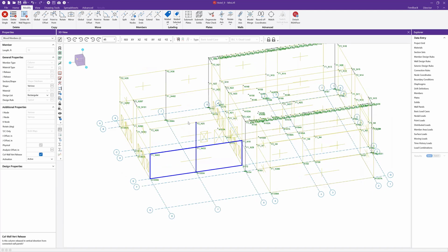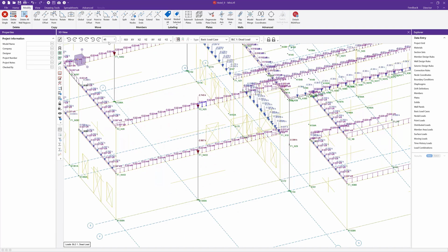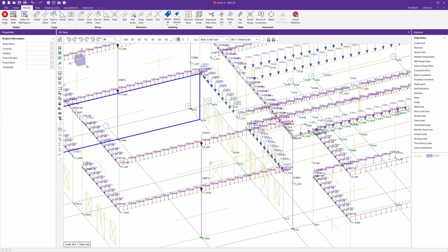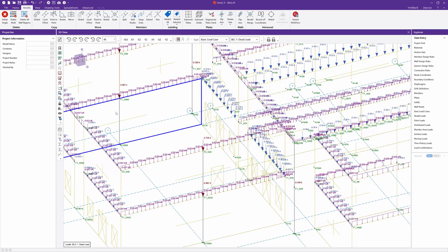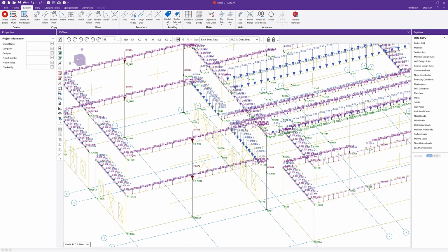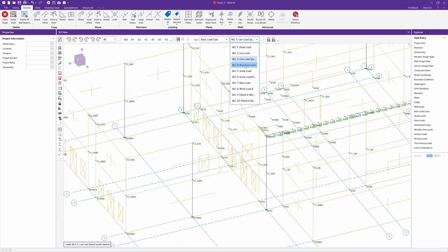So with this, I can also go ahead really quickly and turn on the loads, so I can see my point loads that are coming in from, remember, we had that girder here, if you will, with the elements framing in this Z direction, with the girder framing into the wall at these locations at these columns. So we've got those concentrated point loads in the dead. We've got some in the live, and then obviously we've got some, oops, not special live load, roof live load as well.